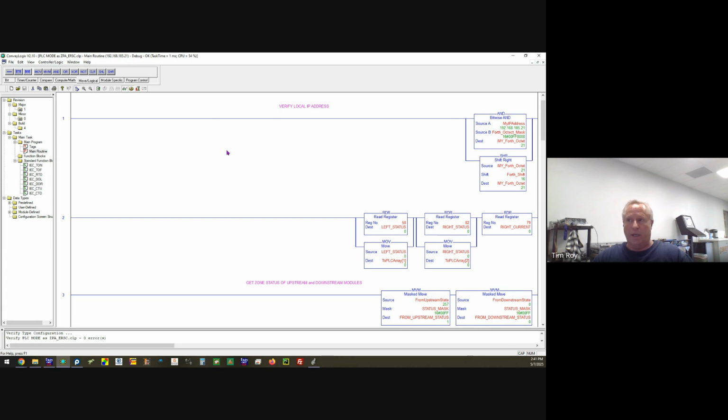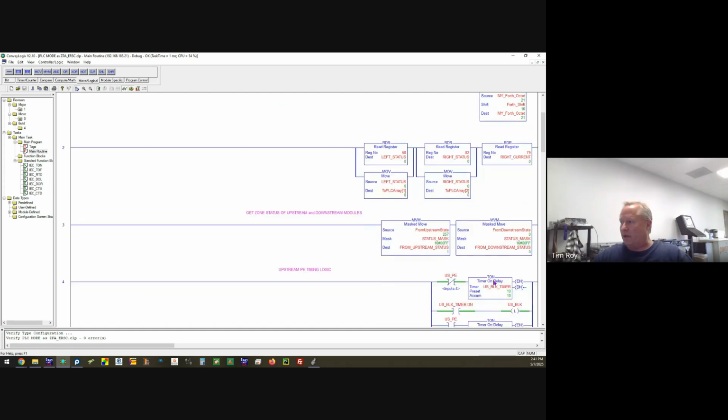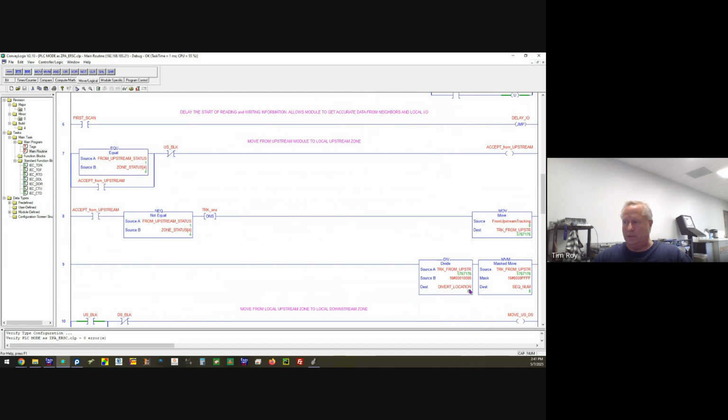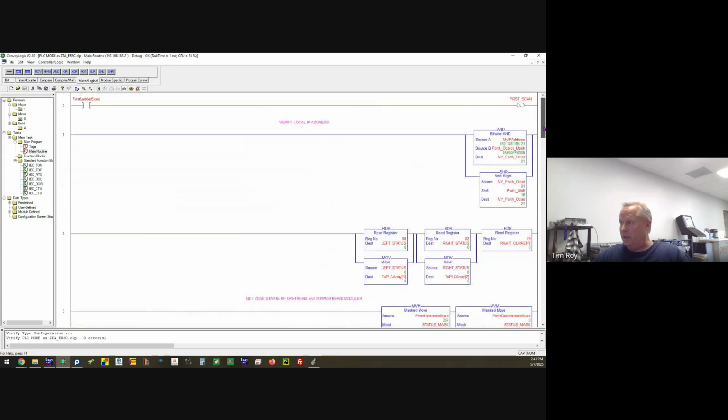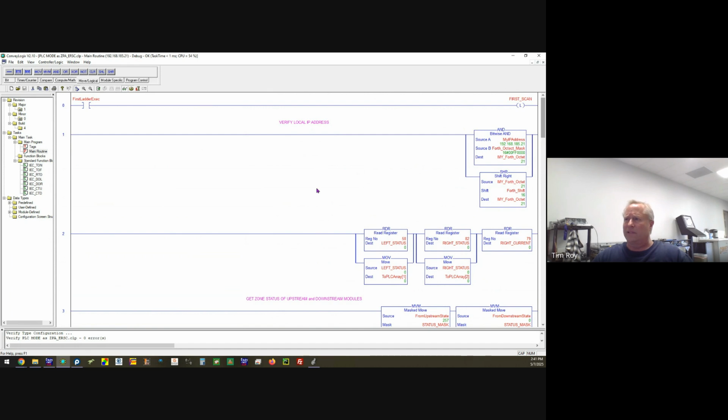So this module here is at a divert location. And I check what's my fourth octet down here. Divert location would actually be the fourth octet. And if this was location 21, and since my fourth octet is 21, that would mean divert. Well, if that's the case, then why didn't you just hard code it as 21 and be done with it? Well, I could have done that and made it really super simple.